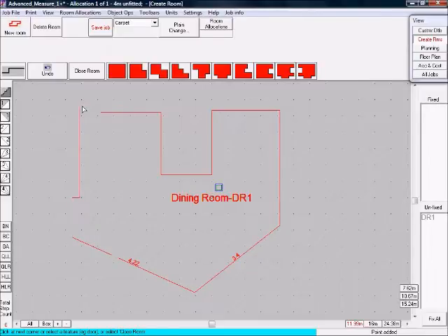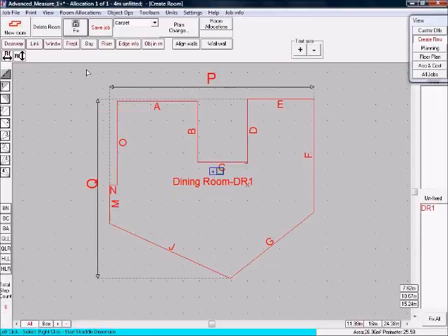Rather than doing a wall-to-wall measurement, we are going to do a corner-to-wall measurement, using the corner between diagonal walls J and G. Doing corner-to-wall measurements is really useful to help anchor the diagonal walls, so look carefully at how this is done.